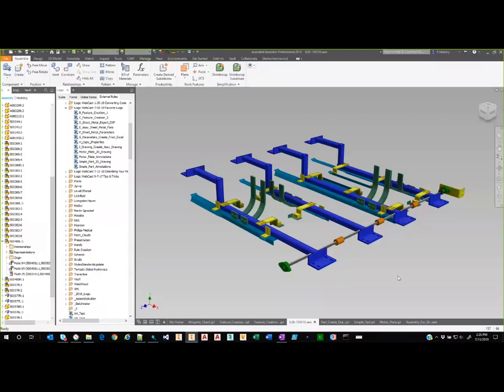I'm also going to set some of the custom format precision. I think I'm setting these to 3 decimal places. I'm turning off the trailing zeros. I'm turning off the unit string. You know, all of those other options that you have inside of that regular parameters dialog box, we can do with code as well. And in this case, I'm making an assumption that the longer of the two is going to be the length, and then obviously the lesser of the two is going to end up being the flat pattern width.